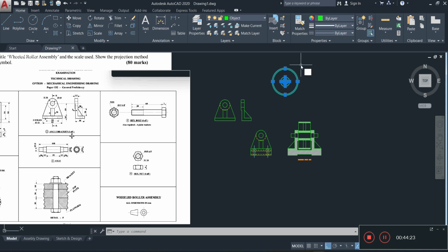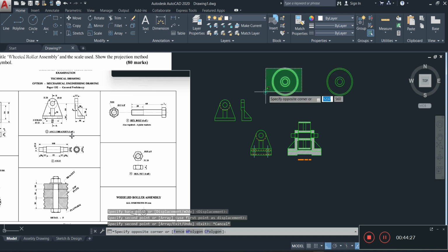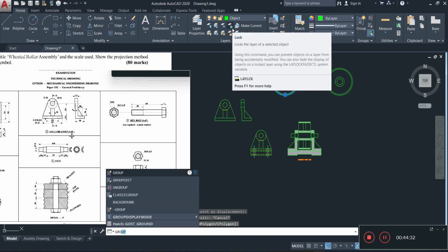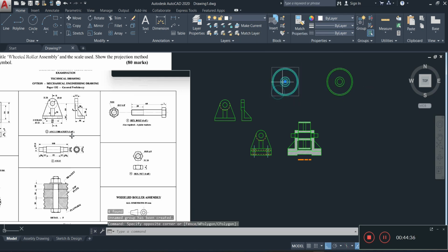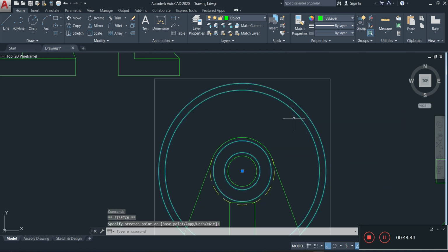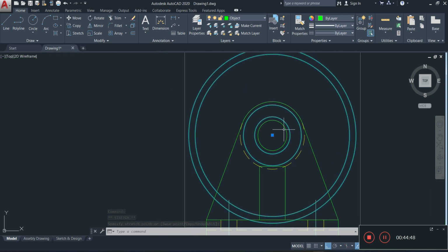making a copy. Should I make a copy? And then I'm going to be grouping this. I should be able to trim while it is grouped, and then I'll just position it into place right in the center like so. Alright, just like that. So it means that all of that portion that you're seeing now, so this circle here and this circle here is going to be in hidden detail line.